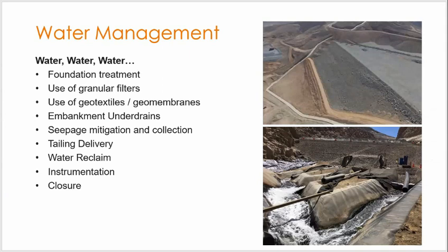So before the thing gets built, you want to make sure you have a good contact between your dam and your foundation. You want to make sure you're mitigating any sort of seepage. Part of that is characterizing the foundation beneath the dam. Part of that is characterizing your local groundwater conditions. And you might grout beneath the dam to provide a seepage barrier beneath the dam. You might excavate a cutoff trench beneath the dam to get down to some more competent bedrock material. But it's really important to avoid preferential seepage paths through the foundation and beneath the dam.